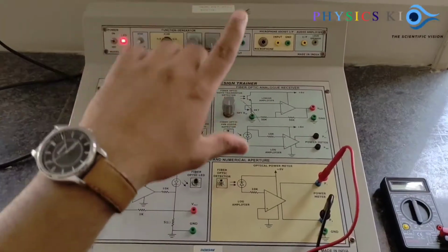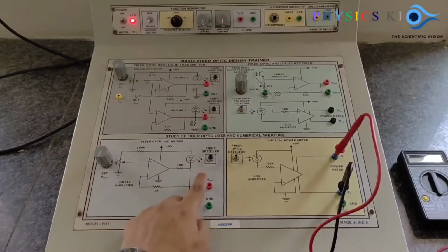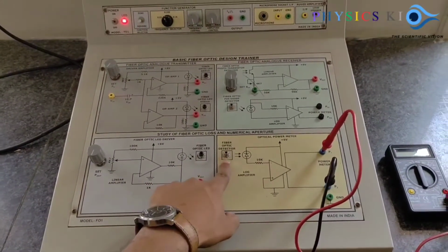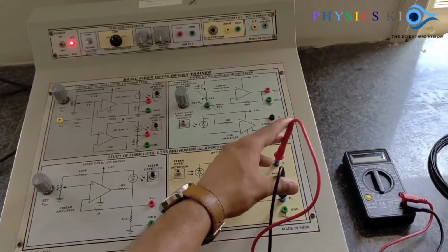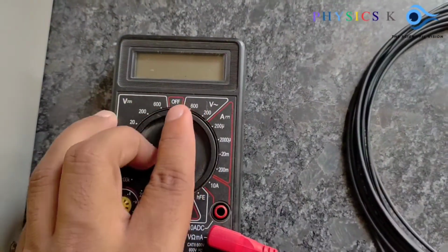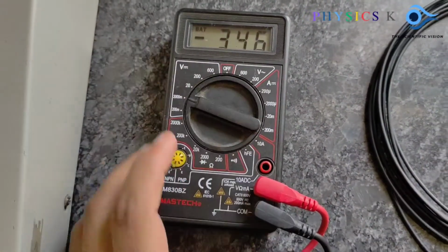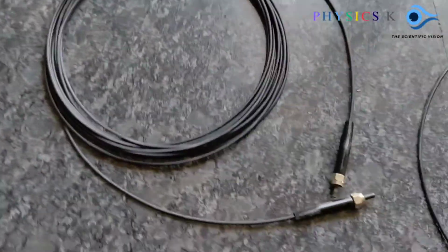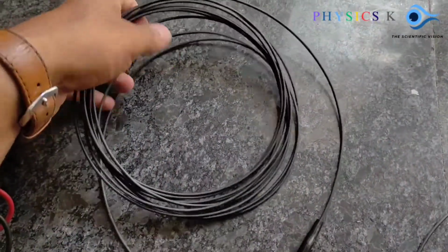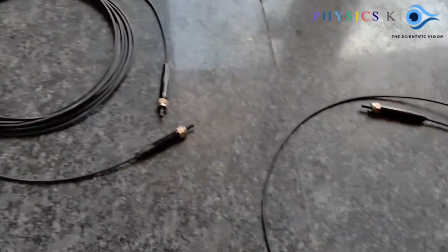So this one is the power loss experiment setup. Knob of power setter, input, output, and whatever the output we can measure through this multimeter. Let's see, turn on this multimeter. Yeah, it is okay. Now we have a 5-meter optical fiber cable, and this one is the 1-meter